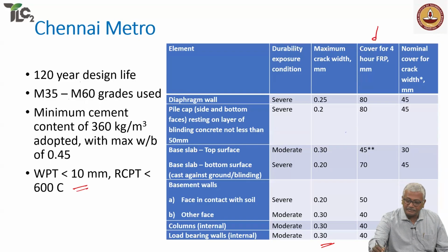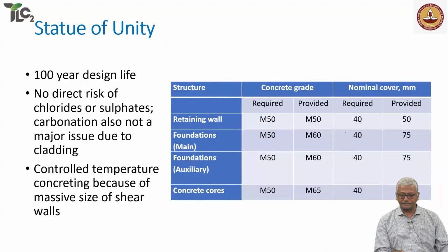They again had a fire resistance performance also, and they defined the cover based upon the fire resistance performance. So all of these depend upon the kind of exposure, the kind of expected issues that you have during the overall performance period. You can then define these criteria and ensure that you are able to meet these demands from the concrete mixture.